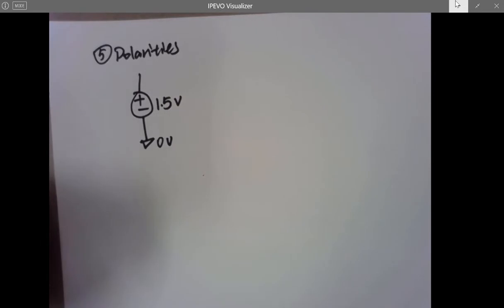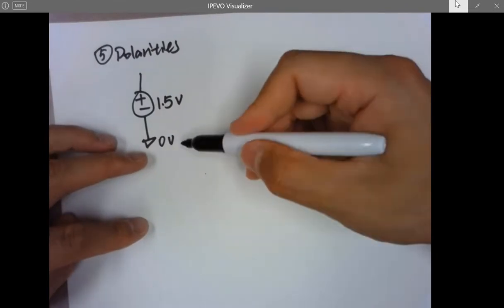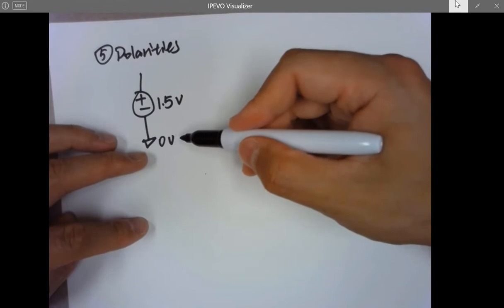If there's any other concept in the future we're going to introduce, for example, you do have a pretty big metal piece being buried underneath the building into the soil, but we're not talking about that. That is a physical electrical ground, but we are not using that always. If we just build everything on a circuit board, a breadboard, we do not have that physical ground. It's always a floating ground, and we just call it a 0 reference.